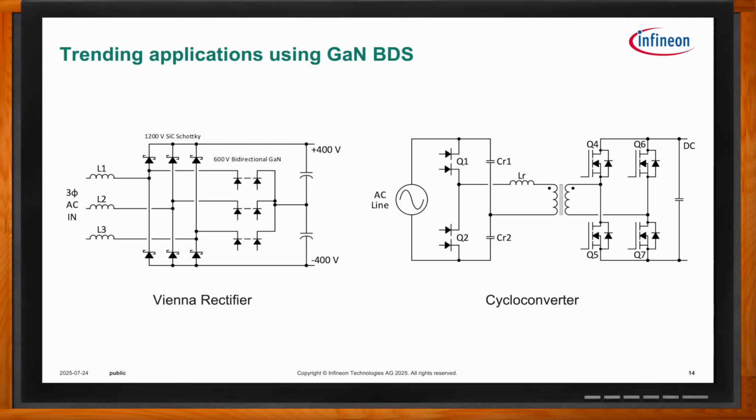It's very flexible. It doesn't have those DC link capacitors, which are often problematic because of their lifetime in high temperature environments like an automotive. So there are a number of advantages this topology has. And like we talked about earlier, it has a battery on the DC side, so the ripple current isn't a problem. All right. So, is there any concern about putting GaN BDS right across the line voltage like this?